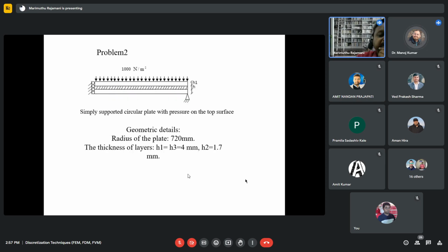Okay. Yes. The takeaway is that whenever you solve for dynamics with viscoelastic material, you get the properties in the form of complex quantities. One is elastic energy, another is dissipative energy. That way the equations are formed, and when you solve for dynamic loading, because the dissipative energy is also present in the system, it gets damped out. So that is the message in this.